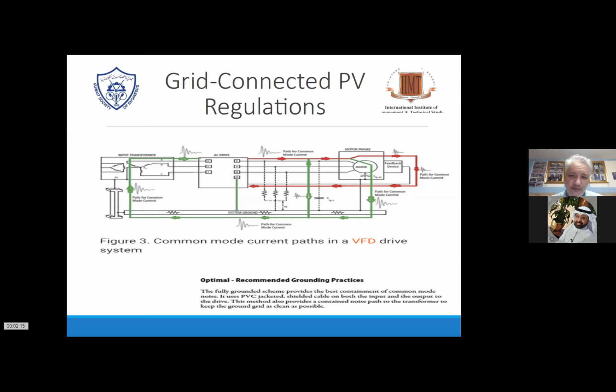When I took off the bridge, the system jump-started again to the old values, because the stray currents went from each individual inverter back to the water pipes and the building, and it destroyed the MPPT capability of the inverter. And the inverter was, funny enough, secondly grounded. I thought I was on the wrong route and the modules were maybe really faulty, till I opened these AC boards and saw that he had made a TNC system out of a TNS system.